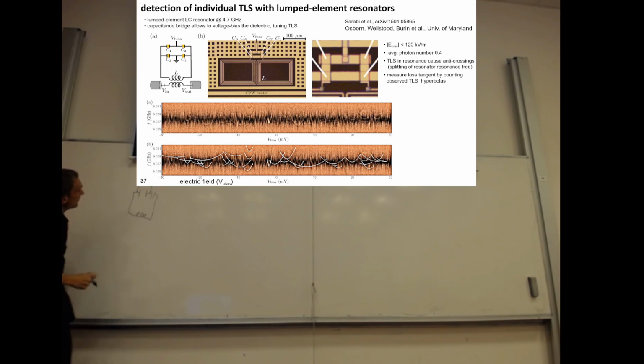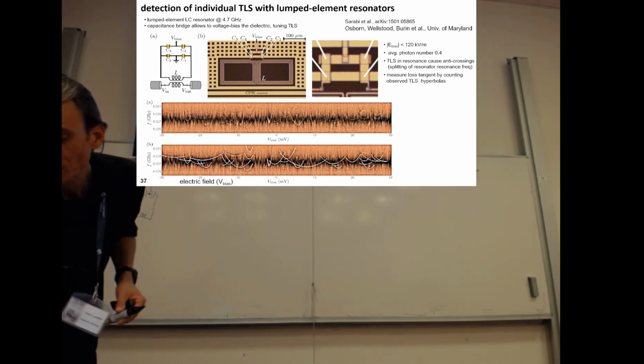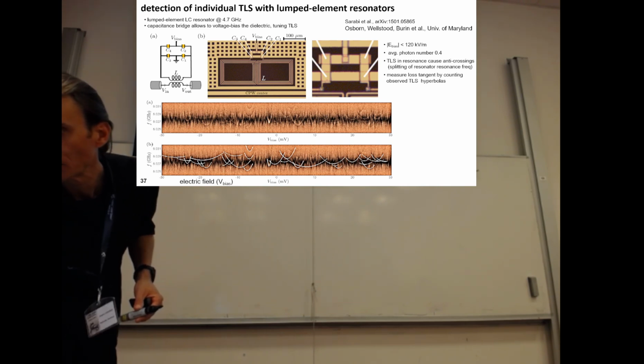But then you don't bias this one. I'm not sure. And of course, it's not good to connect something not in the center here, because only in the center the current is 0, so here you can connect anything and it should not affect so much the quality factor of your resonator.